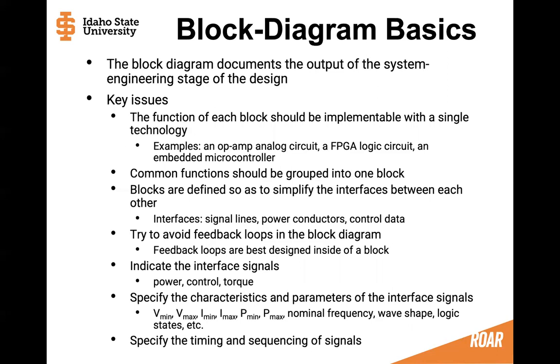Common functions should be grouped together into one block. So if you have maybe a full wave rectifier that is used multiple times, perhaps group that into one block, so you have one full wave rectifier in your solution. Blocks are defined so as to simplify the interfaces between each other. The interfaces might be signals or power or data going through your system. So maybe one block gives data to another block, and they should be simplified so that you can easily see how the blocks interact with each other.